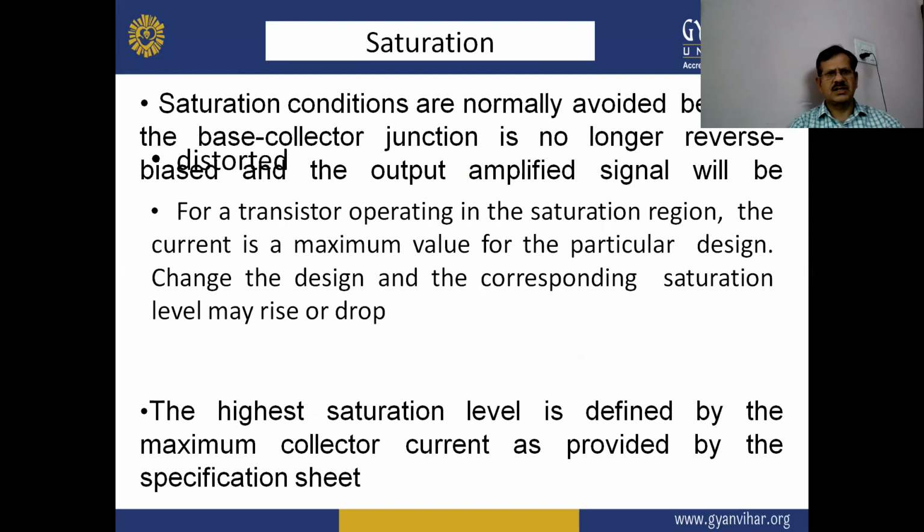What is the saturation? Saturation conditions are normally avoided because the base collector junction is no longer reverse biased and the output amplified signal will be distorted.